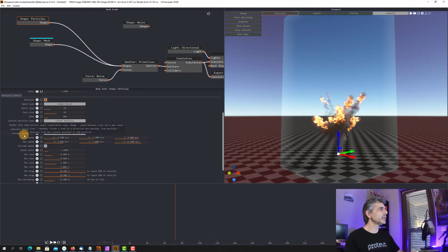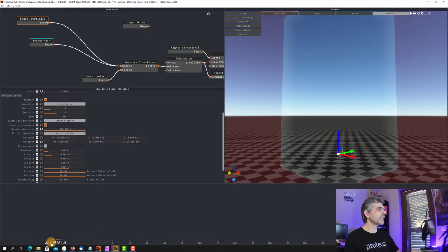And then we have, for example, the speed. So we have a velocity range. So we have particles that are emitted using a specific velocity range. So we have, for example, -3, maximum 3 over the x-axis, and the same for the y-axis. So in this way we have some debris flying away faster and something slower. So something is growing up, something is falling down faster. So, you know, in this way, for example, we have a higher speed. So we are going to launch stuff over the z-axis with a higher velocity. And let's find another compromise between the minimum and the maximum. Okay, you see, that's really simple to control also how the debris are moving.